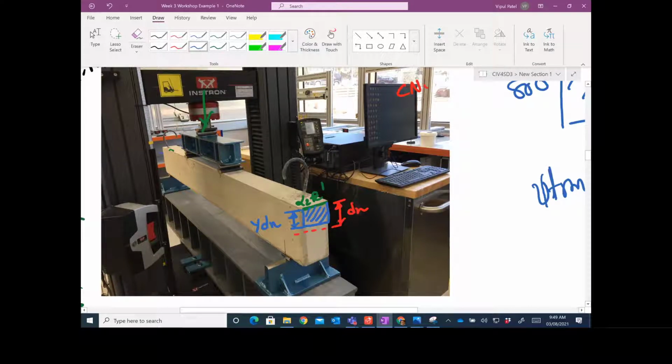So if I want to calculate the force, which is stress times area, the stress is of course alpha 2 f'c. Now the area would be gamma dn times this b. I hope you understand the cross-section area that I am talking about. If you have this stress, then the area would be gamma dn times b, right? So hopefully that makes more sense with the pictures, that you have this cross-section area where you have b and gamma dn.